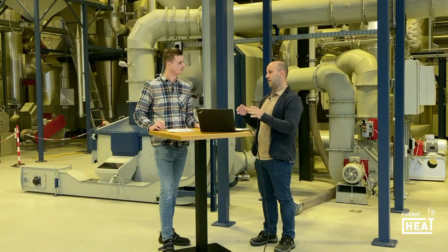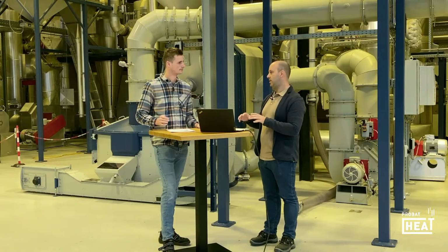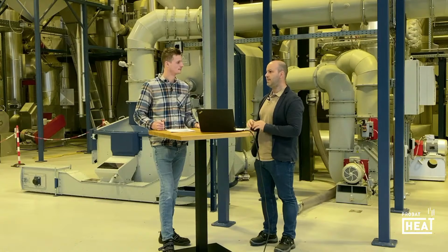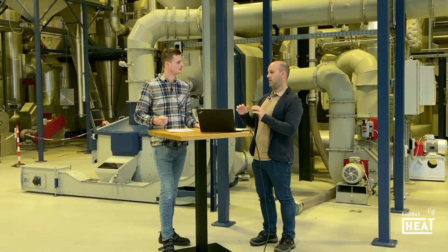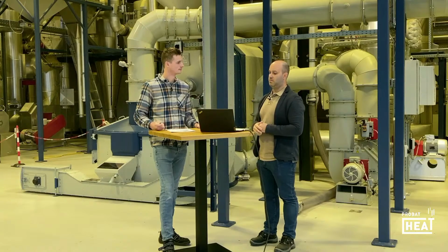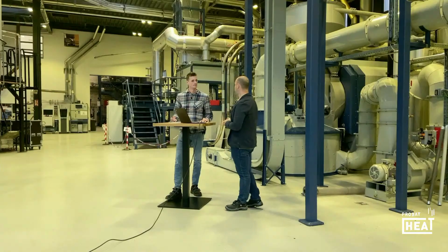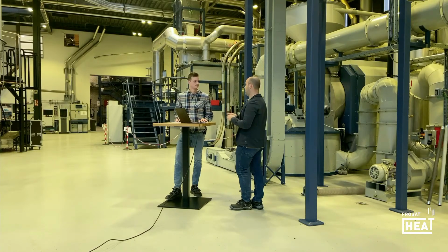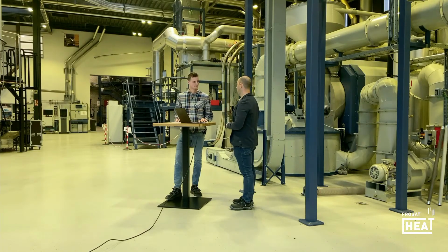And there we are continuously measuring the level of CO concentration. And we have then 2 limit values. If the first limit value is reached, we can end the roasting process, but after that it is all shut down because of a possible safety issue.